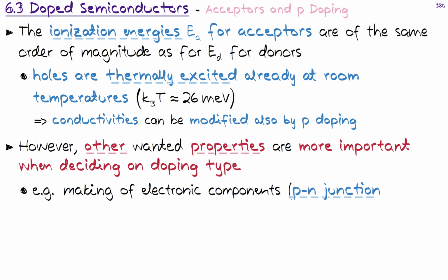And in these kinds of junctions, how they operate is that we want to control the Fermi levels, because if we can adjust the position of the Fermi level in our piece of semiconductor, and then merge two differently behaving semiconductor blocks together, then we can control how easily or how hard it will be for electrons to move from part A to part B.